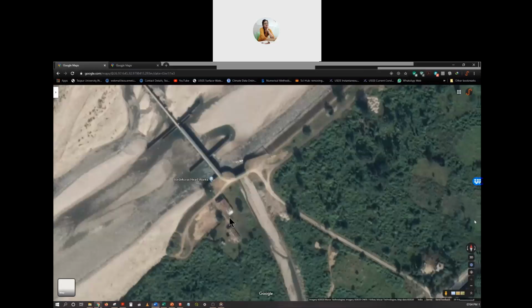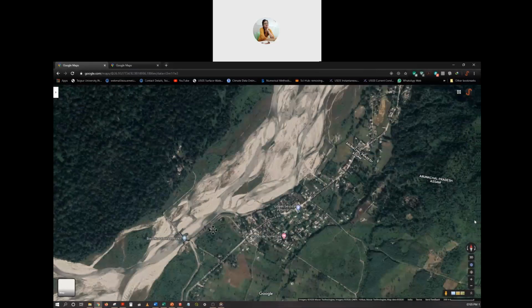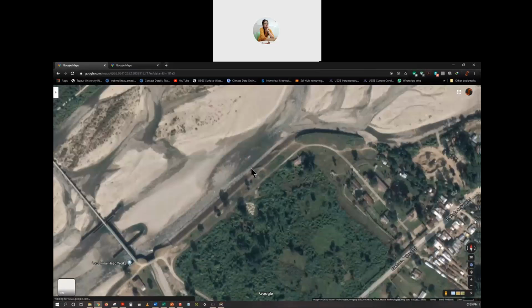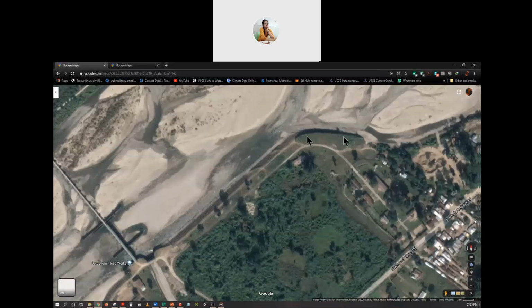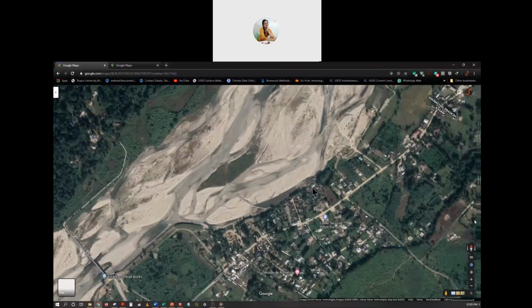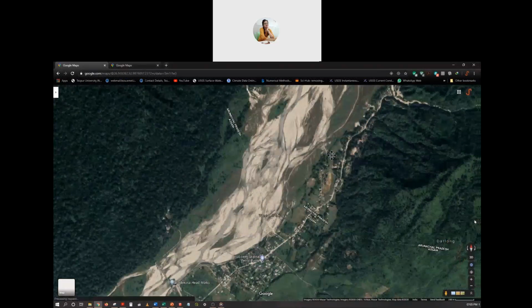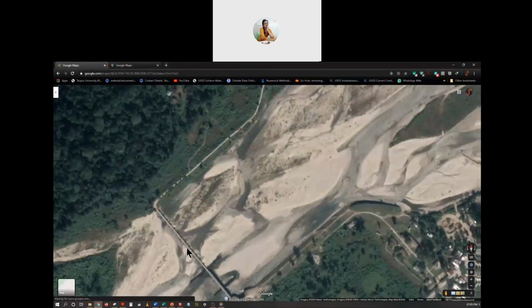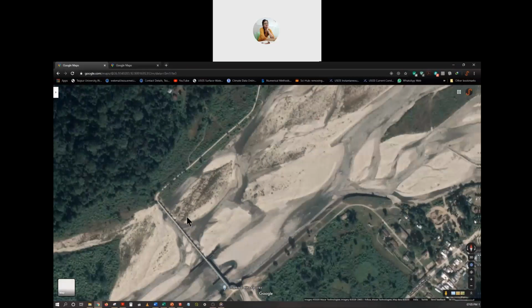That embankment is provided for a very long distance actually, because this embankment which is provided here to protect the bank from erosion is expensive, and it's constructed with rocks and boulders. But a longer embankment can be provided up to a larger length along the river up to the upstream, so that because of this embankment and this weir, the water level is raised permanently, and therefore if flood comes, the flood level will also rise.